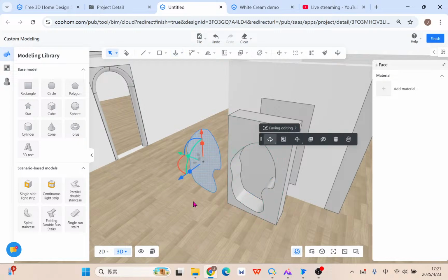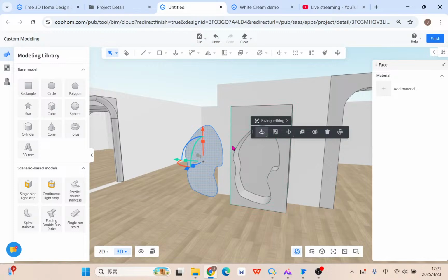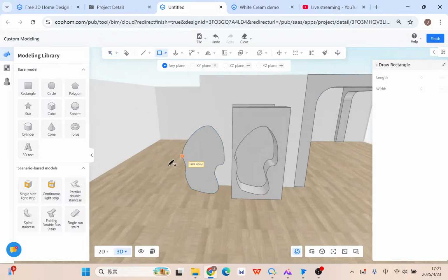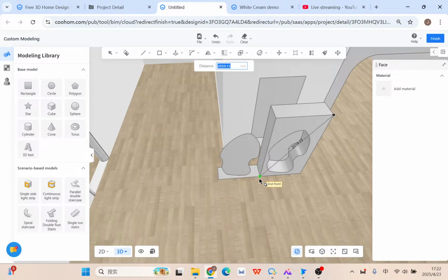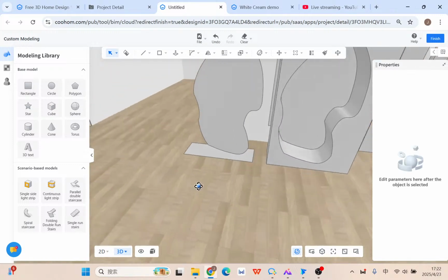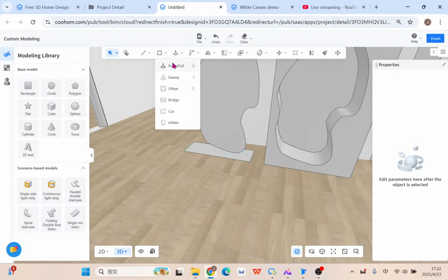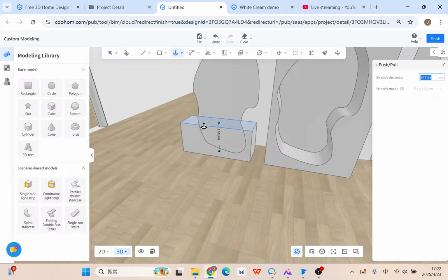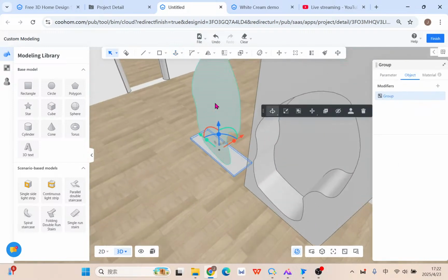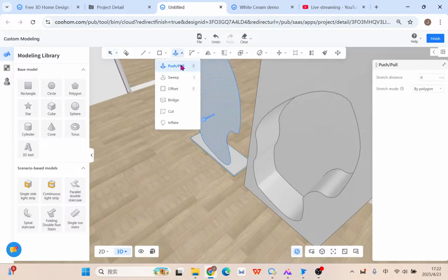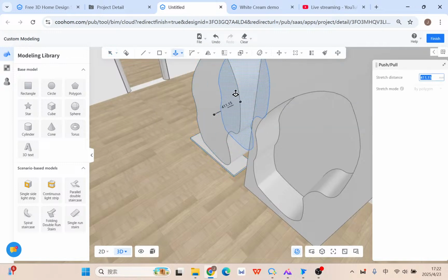And then once you have this, still that's not the end, because for example, I want some more shelves onto it. I can continue to use this one, for example, to borrow here, push and pull, 30, group, right? And still here, I need the thickness.